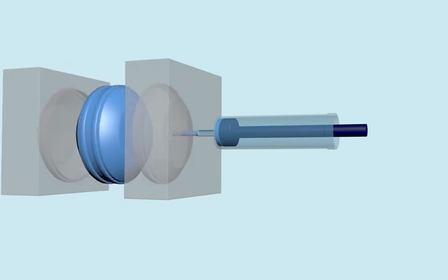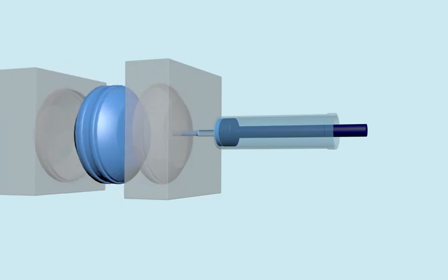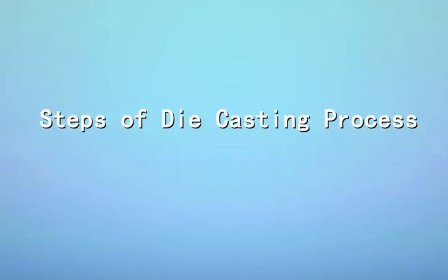The piston maintains pressure on the metal as it fills the die, and once the metal cools sufficiently, the casting is removed from the die, and the individual parts are trimmed off. Finally, each part is machined as required to finish it. Steps of die casting process.